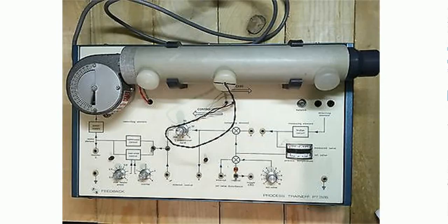This is the PT326. It consists of a fan that, through the opening we can see in the picture, blows air into the tube. We have also a heating element, which is actually a resistor that heats up the air at the entrance of the tube. Then we have the thermocouple. The thermocouple is used to sense the temperature along the tube. We can place the thermocouple at 3 different places along the tube. The thermocouple produces a voltage which is proportional to the real temperature.